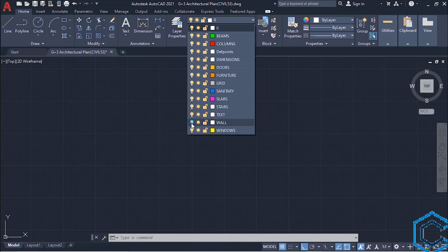Now make a 3 points arc. So go to Home tab, Arcs, left click, and select 3 points, left click. So specify your first point, left click, second point, left click, and third point, left click. Now adjust it to a decent curvature. So select it, and then move it like this, left click.